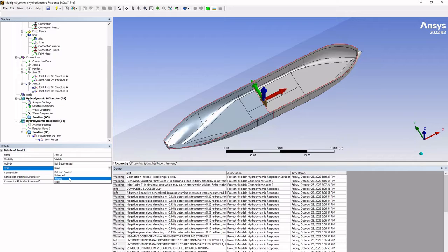However, if the joint is a hinge one or universal one, this axis will move with the structure and rotate with the hinge or universal joint. So it's not the same as the fixed reference axis anymore if the structure has moved and there is relative motion between the structures.